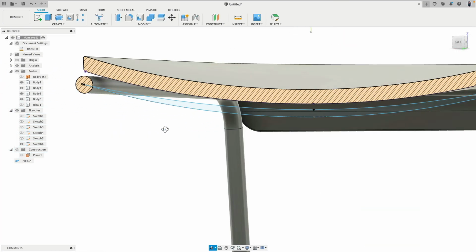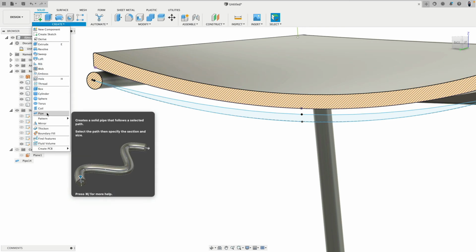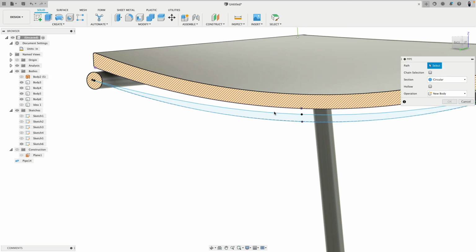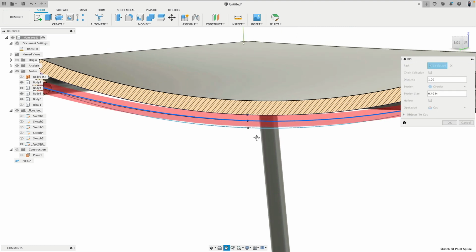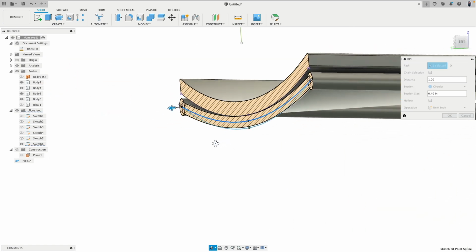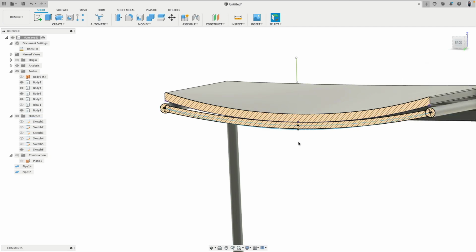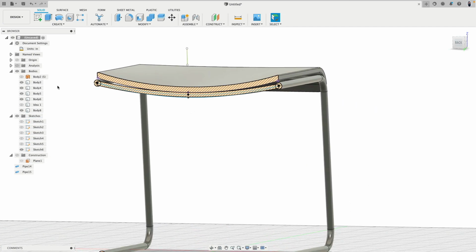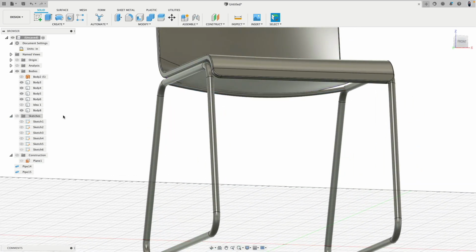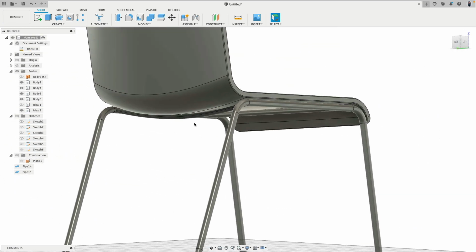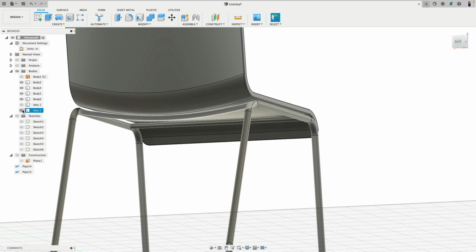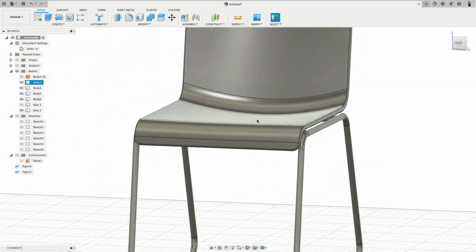This is all fine. So now I make another pipe. Not chain select, just the upper profile. 0.4, all good. And there you can see how this works. I think this was a really good example to show how direct modeling is really good in creating something like this, because then we can talk to an engineering designer client and say, hey, option A, option 2. We put spacers in, now we put a metal bracket, and then with screws we connect it.